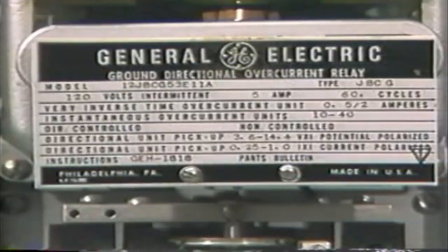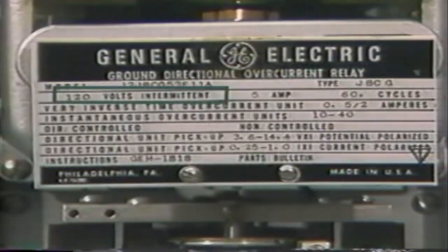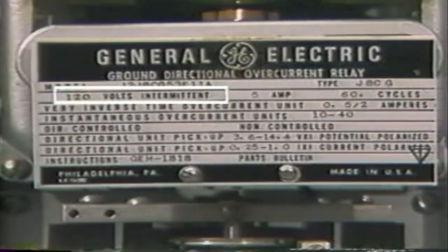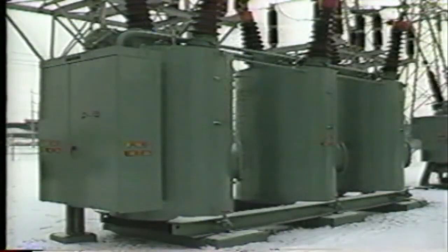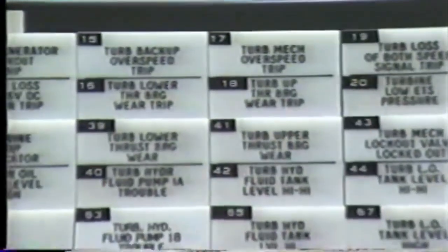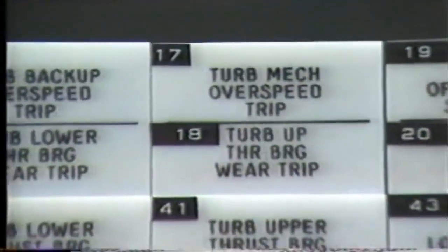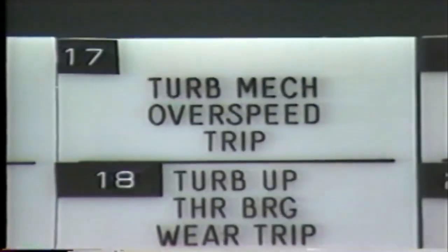Well, obviously, the relay itself is a small, low-voltage control device, whereas the circuit breaker is an integral part of the high-voltage, high-current power system. In fact, for the protective relay to have any impact at all on the power system, it must be coupled to a switching device. The exception to this is where relays are used to give alarm only. But for action, it must command a switching operation.